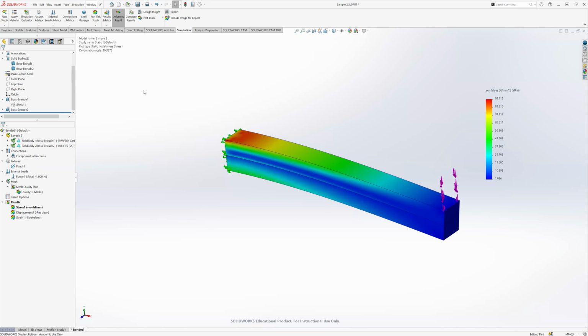I use them all the time. A good example is if you've ever had a part where you're putting a fillet and the fillet is trying to wrap around, and you don't want it wrapping around. You could always split that into two bodies, put the fillet on, and then merge them back together. Specifically for the fillet tool, the fillet can only be applied to one body. You can't apply the same fillet on two different bodies. You can apply separate fillet features, but that same feature can only apply to one. So there are some really good applications of multi-body modeling.